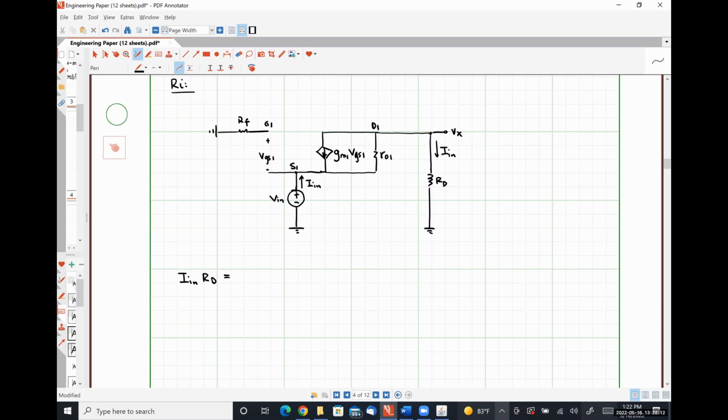All right, so the voltage drop over resistor R01 is going to be R01, I don't know why I wrote 2 when I literally just said R01, R01 times the current flowing through R01. Well, I can call the current flowing through R01 IN plus GM1 VGS1, and that's the current flowing into the negative polarity terminal.